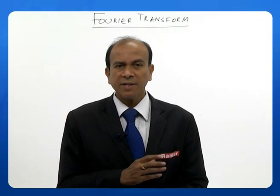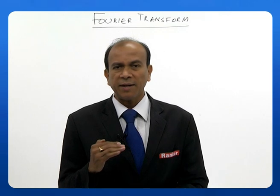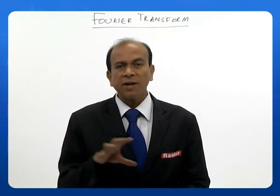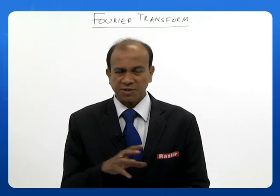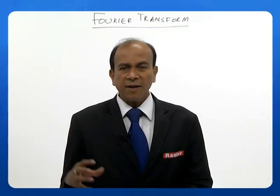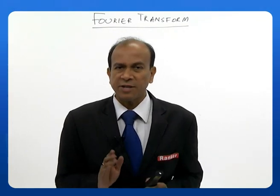Similarly, I take a power signal where limit t tends to infinity 1 by 2t integral minus t to plus t of mod g of t whole square dt, you will get the power of the signal. So if I take the Fourier transform of this, I will get a Fourier spectrum for this called the spectral density. Now when I calculate the area under the curve, then I will get the average power of the signal. So this is the concept of spectral densities.